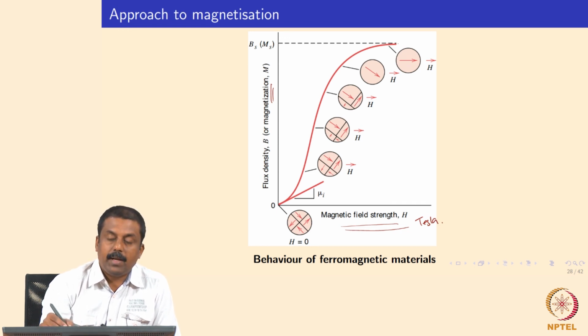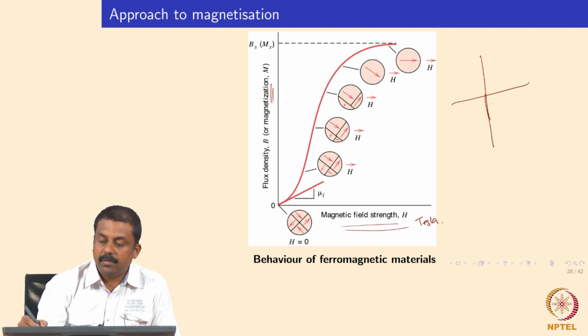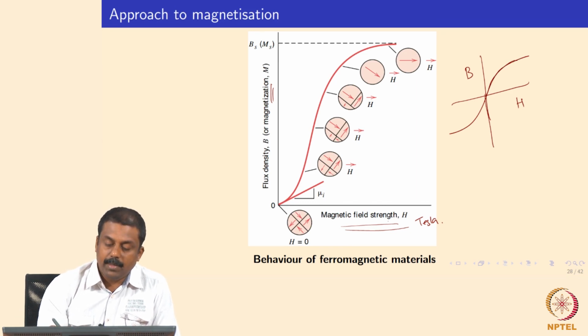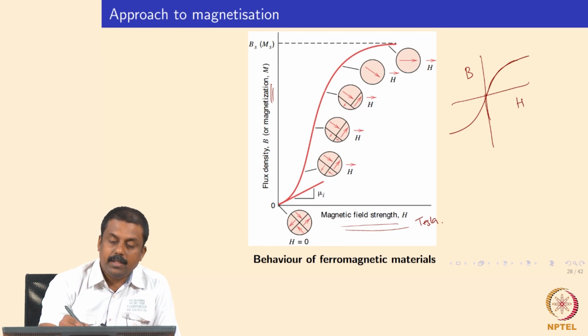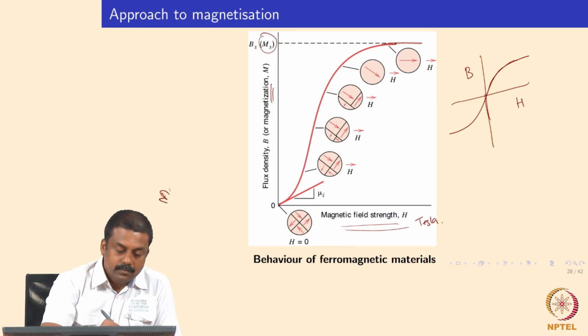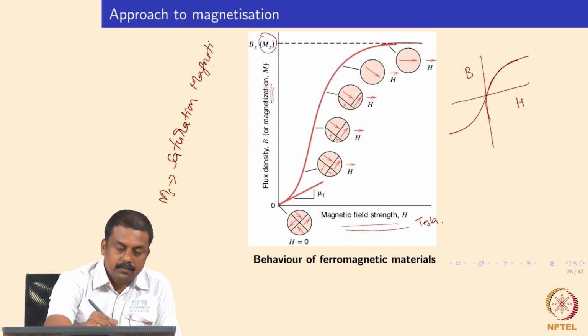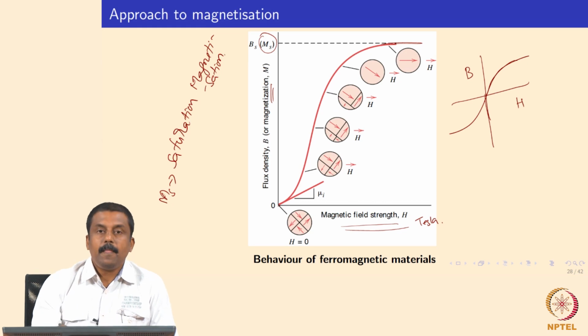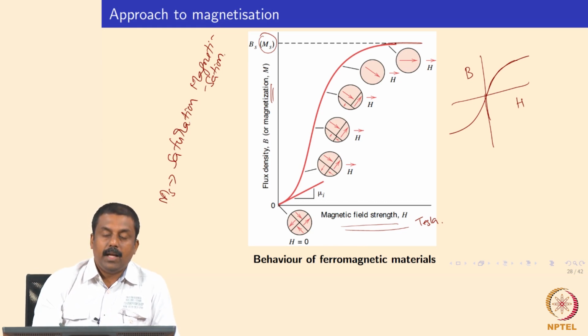So we have a typical magnetic hysteresis curve we must have studied in +2 physics. So we generate such a magnetic hysteresis curve, and if you look at this curve, typically when you start applying a magnetic field, the ferromagnetic material gets magnetized as a function of the applied field, and then upon reaching a critical field strength, the magnetization saturates to a value, and this saturation value is known as magnetic saturation, MS, or saturation magnetization. And this MS value changes if you introduce paramagnetic constituents in the microstructure.